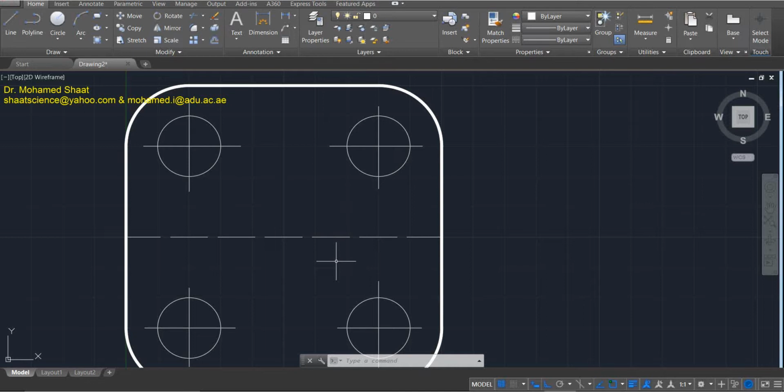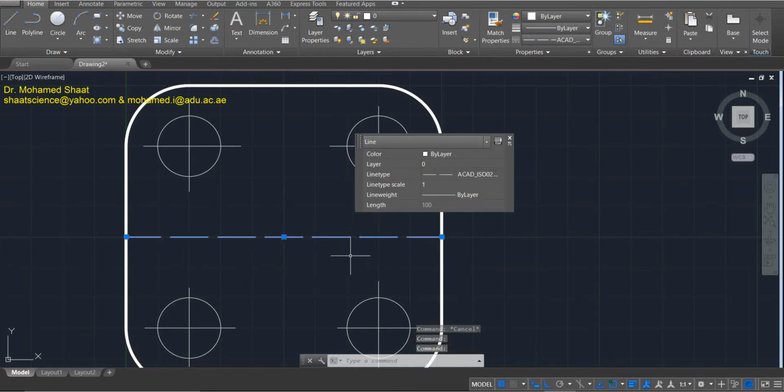We would like to decrease the size of the dash. Also here we would like to play with the scale of the center line, because I don't see it as a center line. To do so, basically, you have to double click into the object. If you double click into the object, as we said, you're going to find a list of some of the properties that have been assigned.